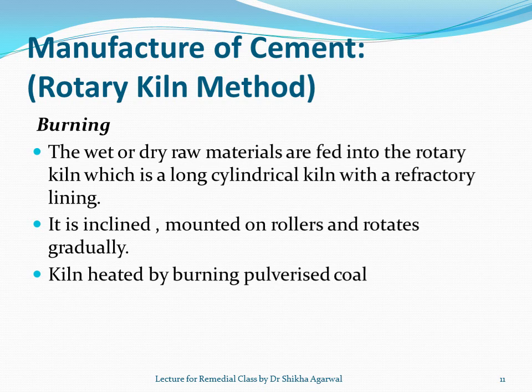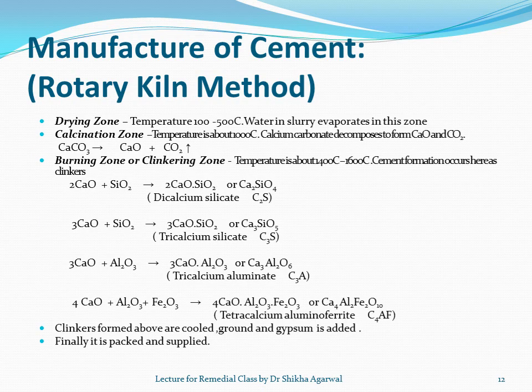It is a long cylindrical structure made up of refractory bricks. It is a huge structure actually. It is inclined, it is mounted on rollers and it rotates gradually. That is why it is called rotary kiln. And this kiln is heated by burning pulverized or powdered coal.